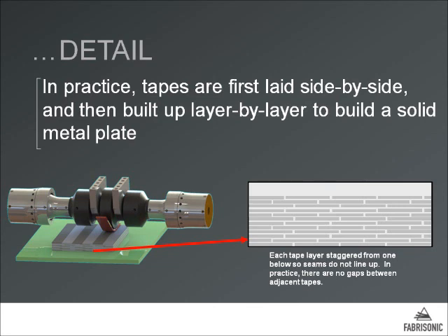So we have this ultrasonic rolling horn that's welding materials by vibrating side to side, rubbing off the oxide layer, and creating a solid state bond. So how do we build up a part? As you saw in the video, we take this process and we just move it left to right. Tapes are laid side by side and then build up layer by layer, similar to a bricklaying pattern.